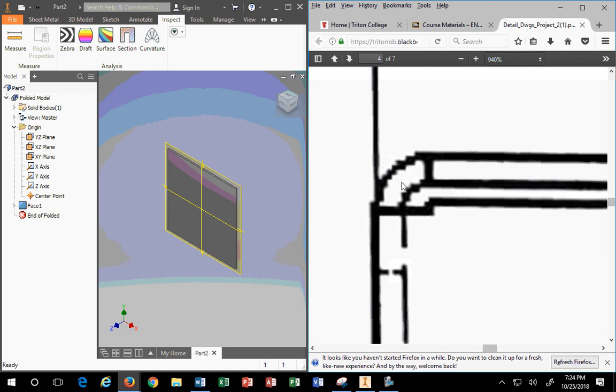If the inside radius is material thickness, which is 0.0625, the outside radius, the natural radius, is inside radius plus material thickness. In our case, it's 0.0625 plus 0.0625. That's inside radius plus material thickness. So what's the outside radius then? It'll give it to us later anyways by default. 0.125? Yep. Because it's a 16th plus a 16th. Correct.